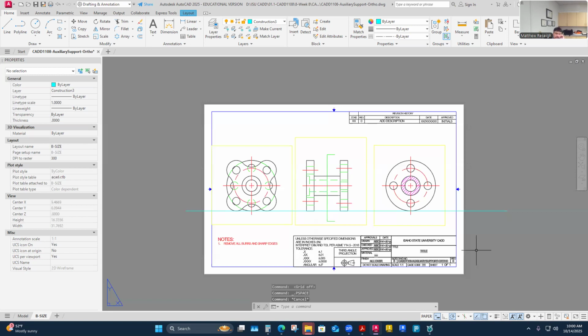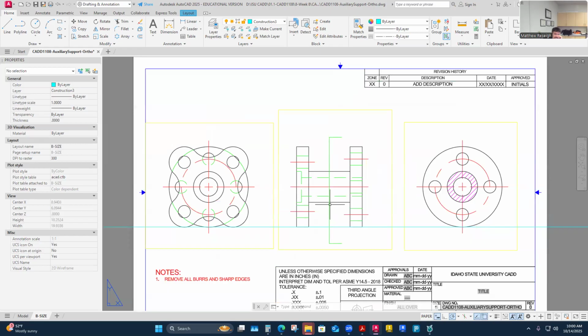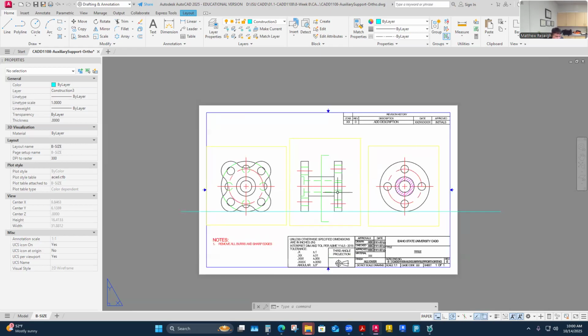Yeah, this is heading the right direction to detail now. Obviously, I have line type scale issues. They're pretty coarse center lines and pretty coarse hidden lines actually. So I'm going to make those a lot finer at the very end. I'll just start dimensioning. So break this down piece by piece. A little bit of time. Whether I finish this or not, I don't know, but I'll finish it out on the video and post it up as part two. So I'll just keep going until I'm done.